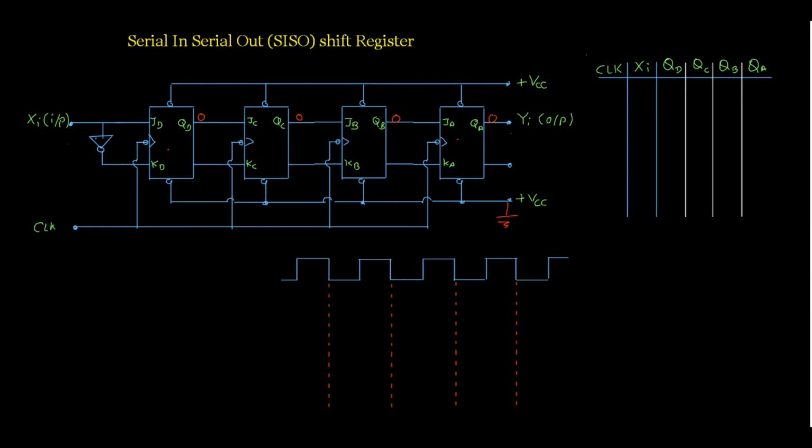After clearing the SIPO register, you have to remove this ground and apply the VCC. So when the preset input and the clear inputs are high, then we have a normal operation of the SIPO register. We have normal operation of the flip-flop, correct? Now let us apply 4-bit data.